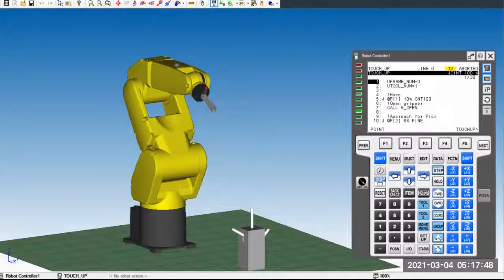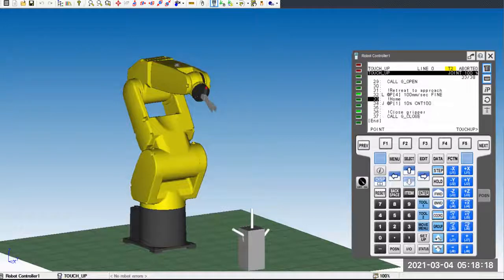First, let's run the program. Notice here, when I run the program with shift forward, you can see the screen flickering, right? It looks like it's running, but the robot doesn't move, because you can see here I asked you to teach all the locations. You can see the add symbol is on P1, P2. If you go down here, also on P3. So all the positions, P4, right? All the positions in this program are actually the same position, which is right here.